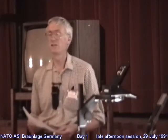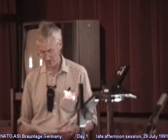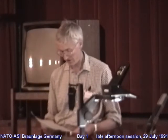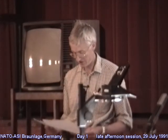So we conclude that although there is strong evidence for the existence of the adhesion component of friction, it is a controversial subject. I like Professor Johnson's term, tangential interaction, as a less confusing term than adhesion, even if it's not such a compact term to use.